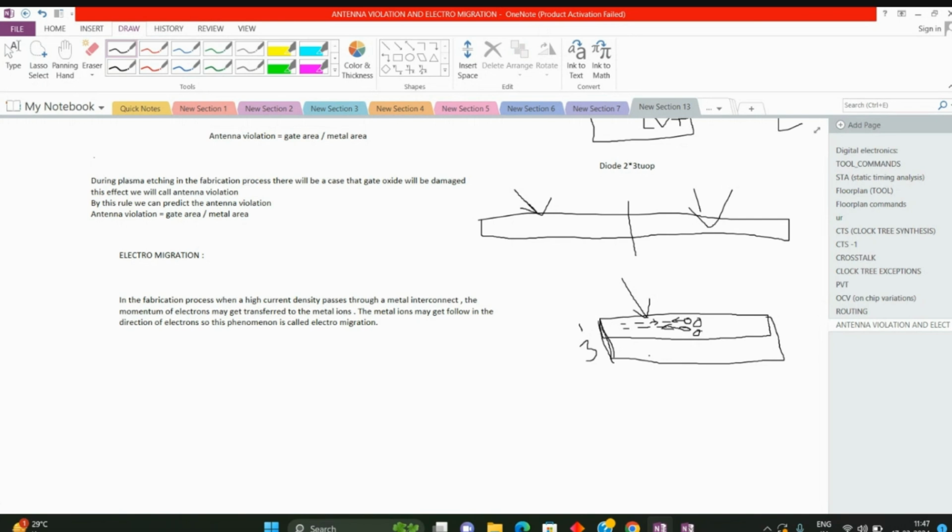So in this case you won't apply blindly. If there is an antenna violation in your design, don't go and apply an antenna diode over there blindly, you can't do that. First you need to do the simplest things. Adding the antenna diode, or increasing the width of the metal layer, these will be secondary cases. Maybe for you, these are the main fixing methodologies for antenna or electromigration, but normally in reality these will be the secondary cases.